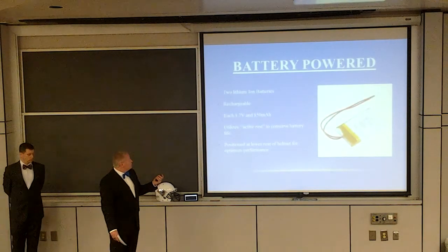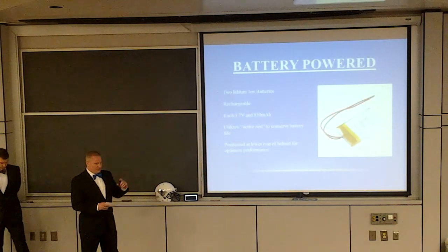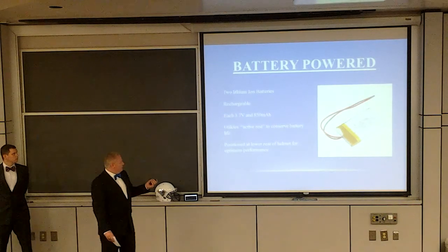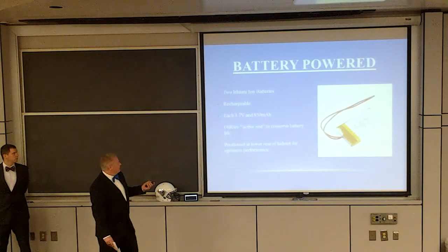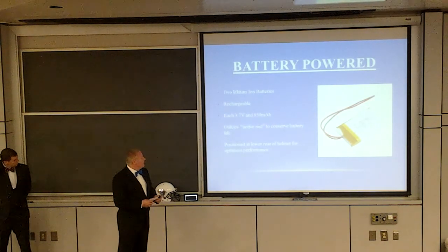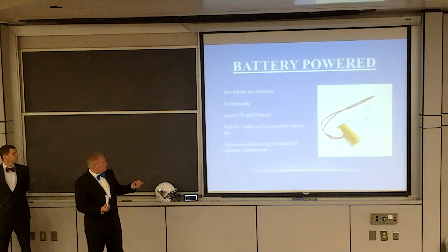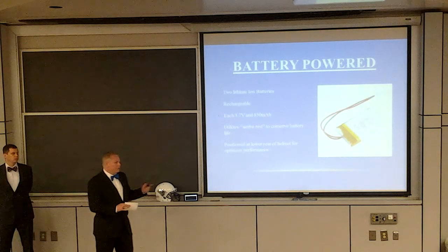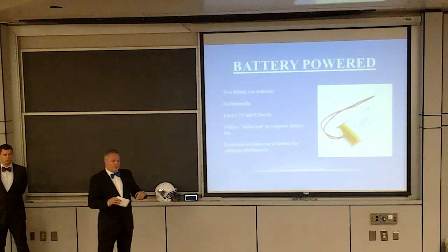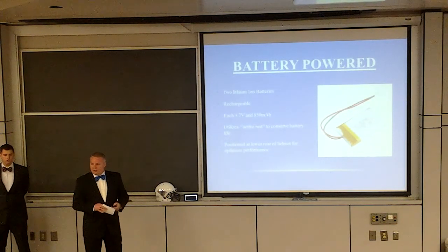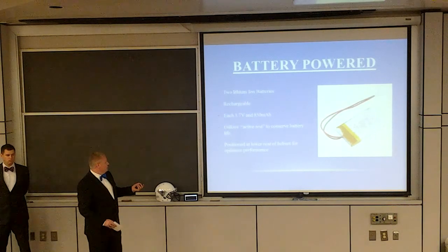The batteries we chose are 2 lithium-ion batteries. They're both actually very small and very thin. They each are 3.7 volts, and they have 350 milliamps. The Bluetooth uses active rest, and so does the Arduino, to conserve battery power. So when it's not being read, it's using very little power.